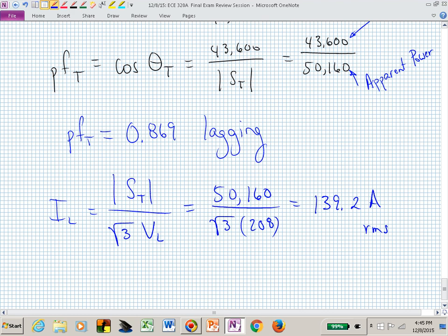Is that a safe amperage? No. Okay, if you want, you would probably hear that. It would be buzzing. Okay? You would stay away from that very far. Even if you divided that by 100, it's still not safe. 1 amp is very dangerous. 100 milliamps is not good. You can't even let go of 100 milliamps. 0.1 amp.